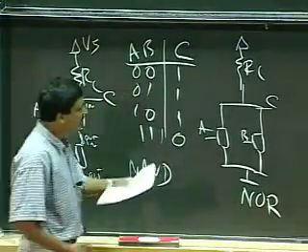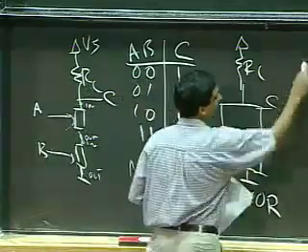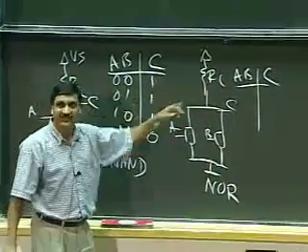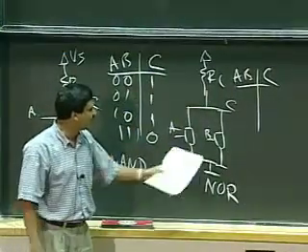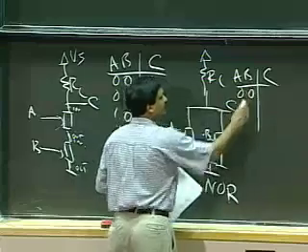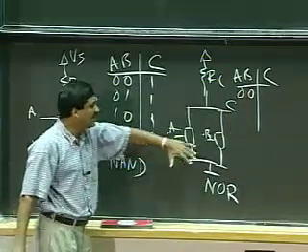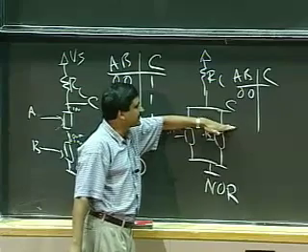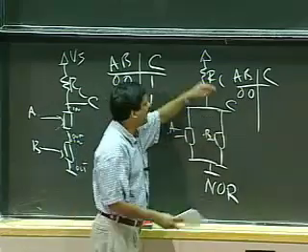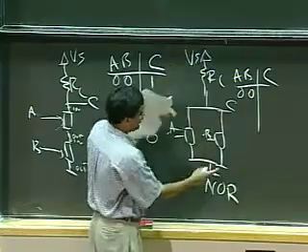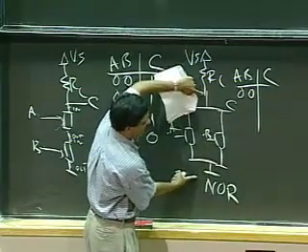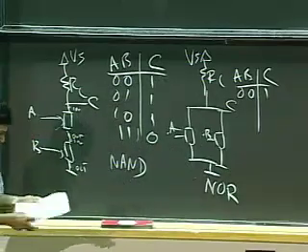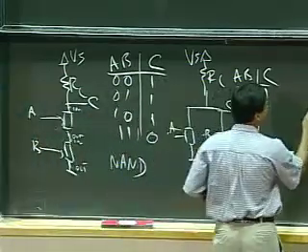So you can go home and practice a truth table for this. A, B, and C. I'll just fill in one of the rows. So in this particular situation, if A is 0 and B is 0, both the switches are off. So it's as if this little sucker here is cut off from ground, and Vs falls across from C to ground here, and the output is a 1. So on and so forth. So I can build other interesting forms of gates.